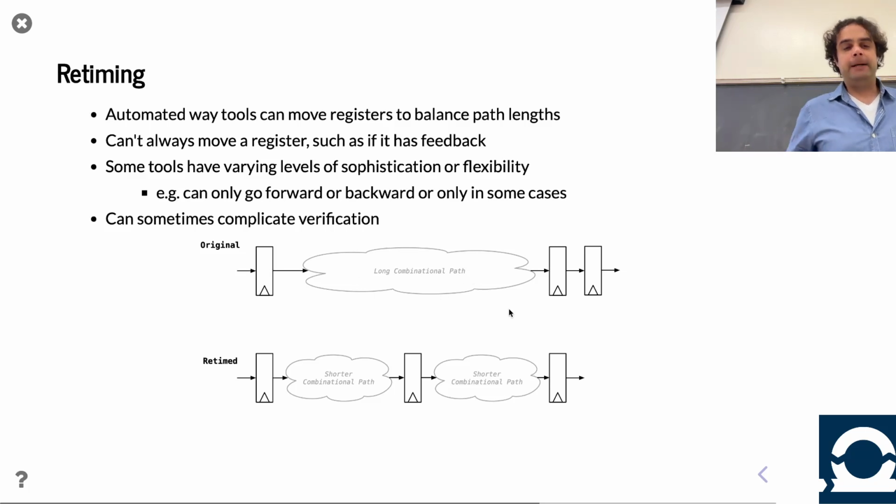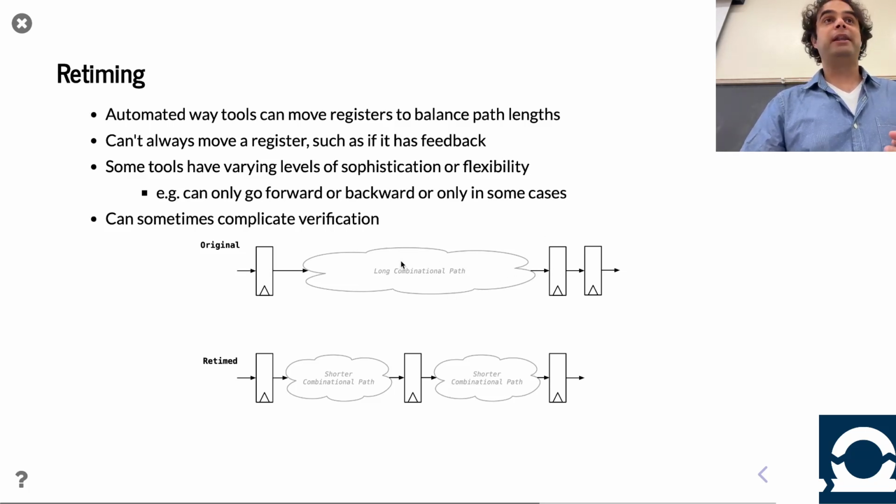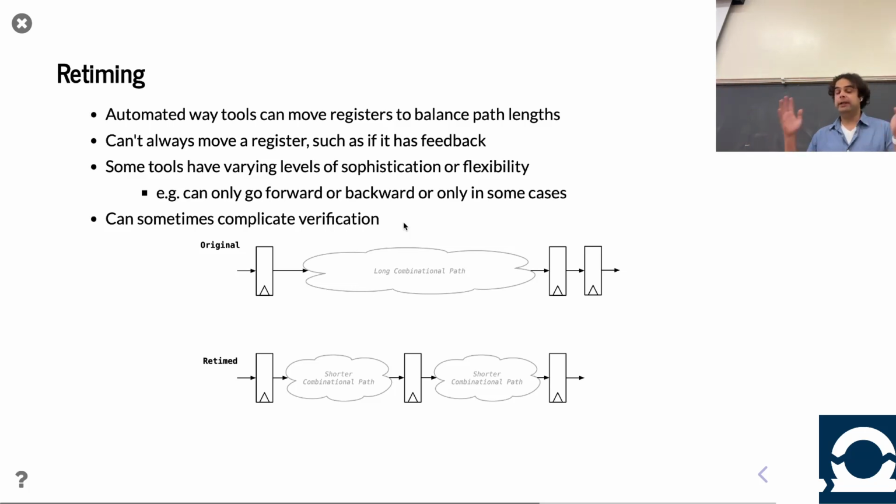Now, sometimes there are situations where topologically, if it moves the register, it's going to cause certain challenges. For example, maybe you have a 4-bit bus here. If we move back too far in this path, what was a 4-bit register now needs to become an 8 or a 12-bit register. The tools can figure it out, they'll do it. Other times, you have topological constraints where it really can't move registers. Maybe there's some tight feedback path, and moving it there is going to break it up. It's going to do the best it can, but obviously sometimes there are constraints, right?